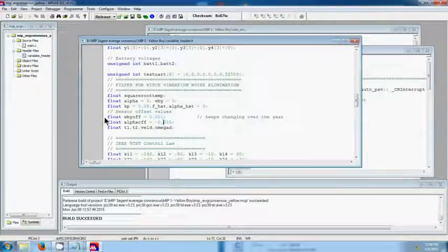The center of gravity of each agent is at a different location, hence a different pitch offset value has to be added to each agent. So care has to be taken not to recreate files just by copying from agent 1.